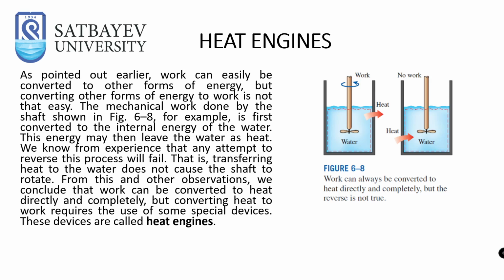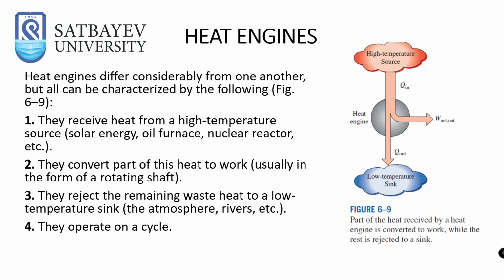This energy may then leave the water as heat. We know from experience that any attempt to reverse this process will fail. That is, transferring heat to the water does not cause the shaft to rotate. From this and other observations, we conclude that work can be converted to heat directly and completely. But converting heat to work requires the use of some special devices. These devices are called heat engines.